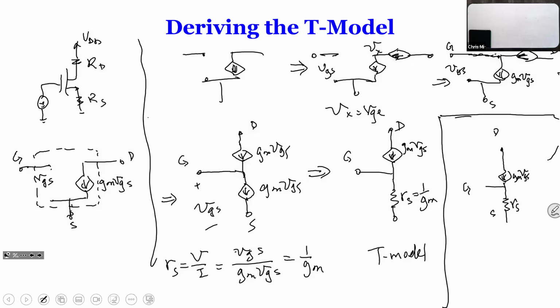So now tell me, what is connected to the gate? This is the first step: take the MOSFET out, draw a small-signal equivalent circuit, and then the second step is to find what components are connected to each terminal. So from that circuit over there, what is connected to the gate? Now, neglecting DC, just look at small signal. That's the voltage source, right? So we have a voltage source connected, which in this case we're going to call Vin. We're not going to call it VGS anymore because that is your input. That may not necessarily be the same as VGS, okay?